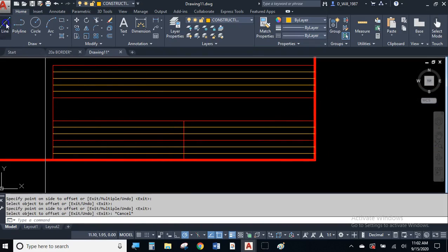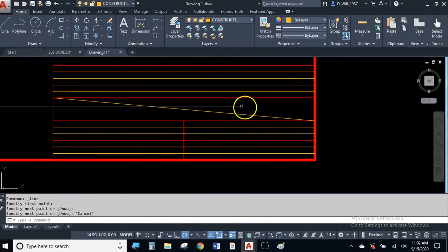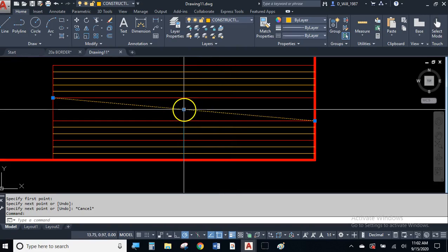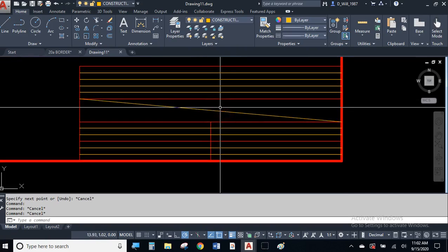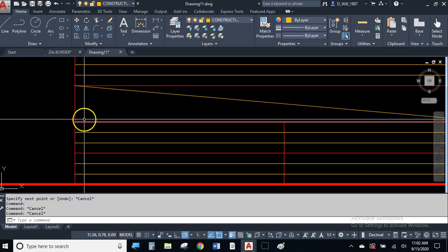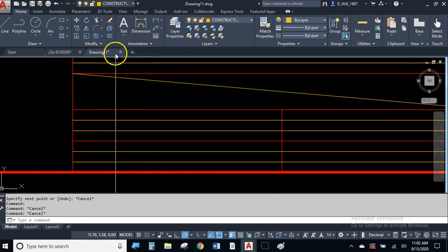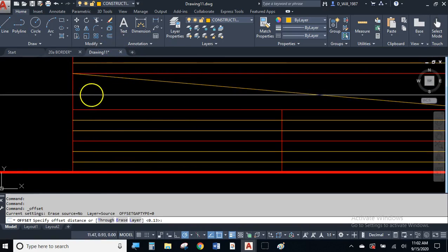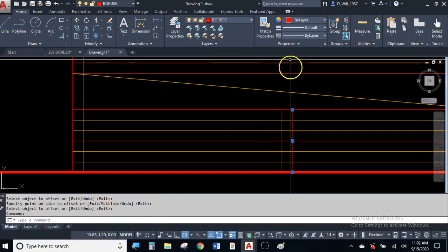The middle box, we said we want it middle center justified, and here is the diagonal. That will help me find the midpoint inside that box. Alright, so you can think of those as guidelines. I also need some on the bottom here for the text, so I'll do my offset. We'll go to the right an eighth, and we'll take this guy and we'll come over an eighth to the right. And that is another construction line.